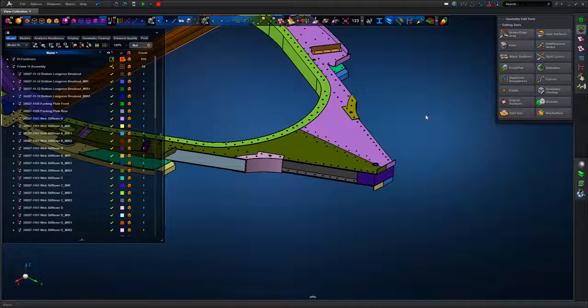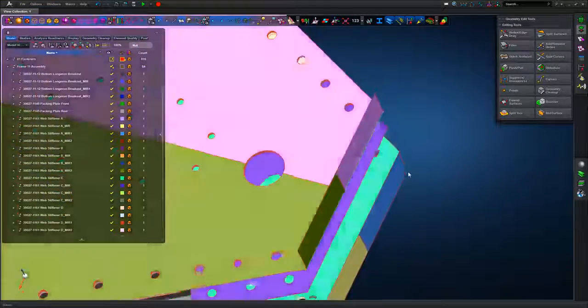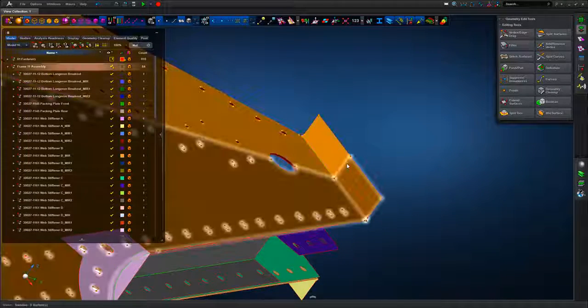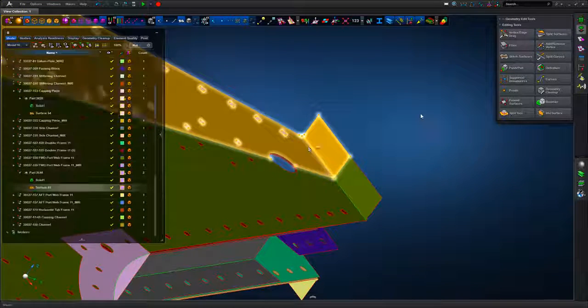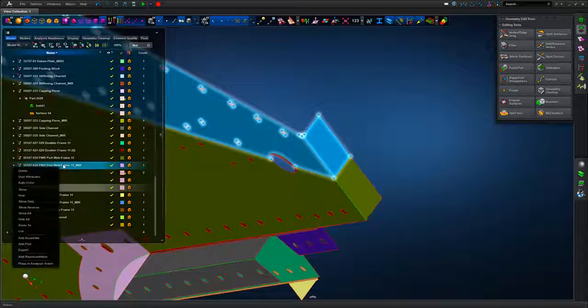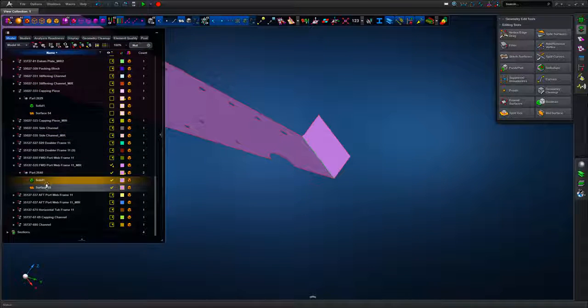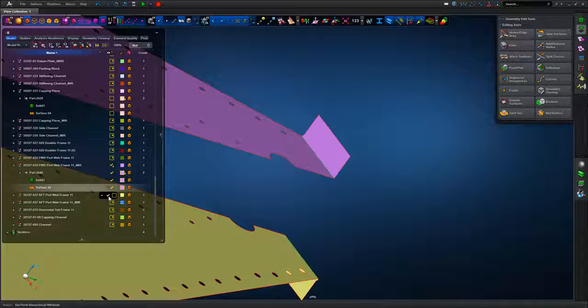We can turn off the solid and show the free edges. So these are the mid-surfaces that have been created, and each mid-surface is contained within the parent subassembly part where each solid was defined that was used for the underlying mid-surfacing operation. So we're just going to center it in browser, look at the discrete part definition, and then we're going to move the adjacent mid-surface that's created. So just looking around in the model browser tree for the adjacent paired surface, as it were.